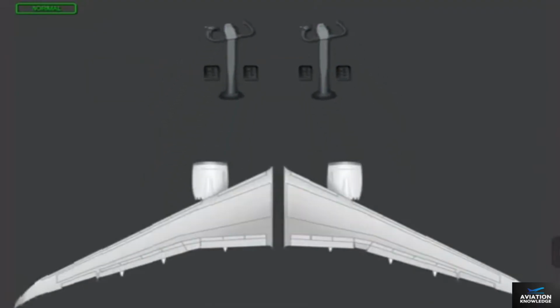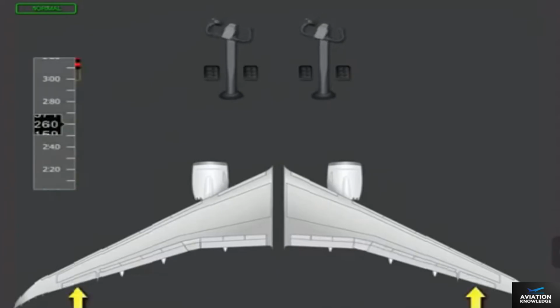The flight control system automatically positions the ailerons, flaperons, and spoilers to generate the commanded maneuver. At high speeds, the ailerons are locked out and only flaperons and spoilers are used for roll control. Automatic control surface commands minimize airplane roll response to turbulence. The system will constantly monitor airplane responses to pilot inputs and reposition the lateral surfaces to carry out these commands.